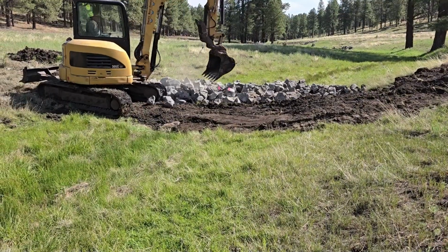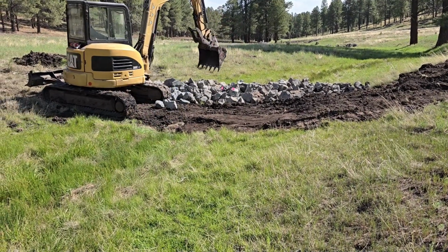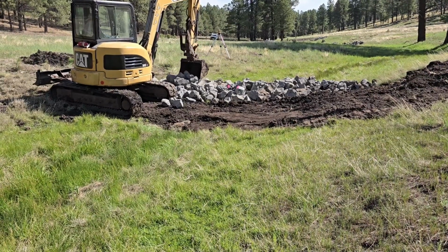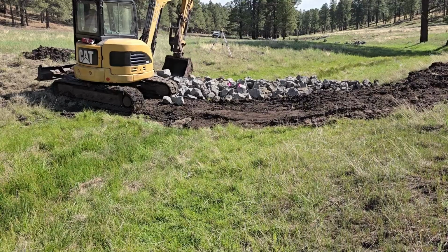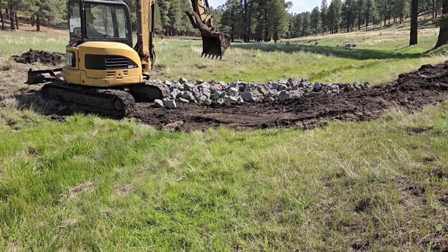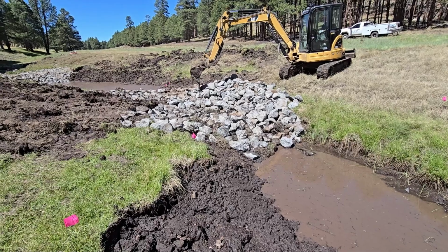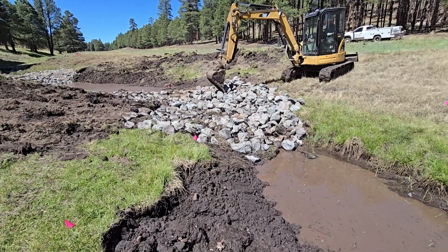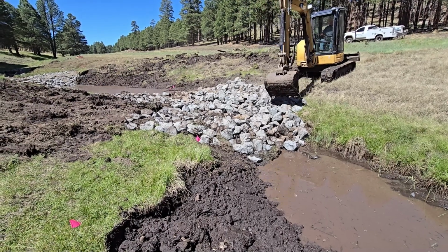We begin moving the piled rock over the groundwater dam. The rock is placed to armor the top of the groundwater dam, which is the entrance to the spillway and is also the wetland outlet. Don will travel over the rock to push it into the ground and will rearrange the rocks so they fit tightly together. We're moving rocks from where they are piled up on the slopes of the valley so floodwater won't cut a channel around the rock. These rocks will also be pushed into the ground so they don't wash downstream during a flood.